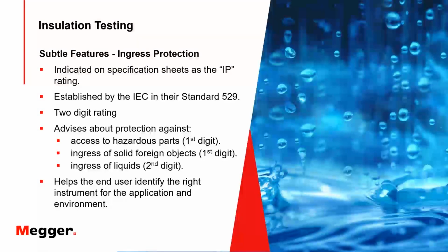The dust in that kind of atmosphere can take your equipment out of service sometimes in a matter of months, because all of that will get inside the equipment and degrade the circuitry. The second number has to do with moisture. So if you're in an environment where there's a lot of moisture spray and things like that, you want to have maximum IP rating. So look at your IP rating. The higher the numbers, the better. If you have a low IP, you can't take that into any kind of a demanding physical environment. Okay, next.